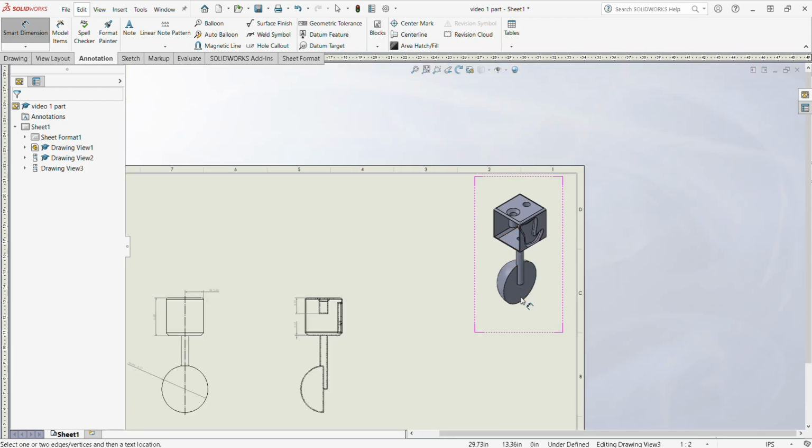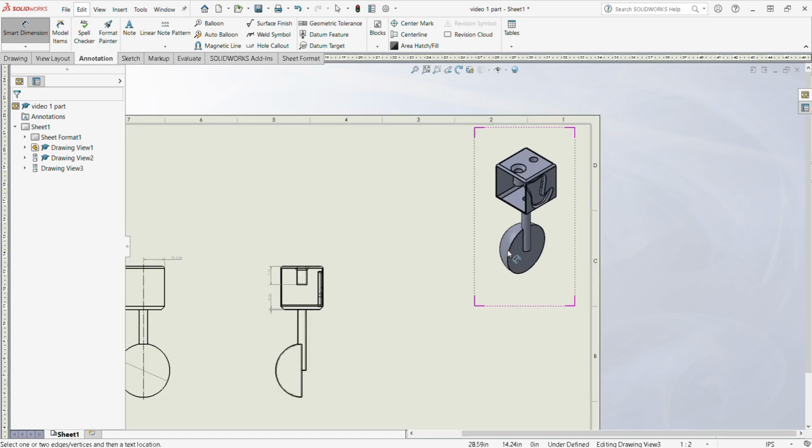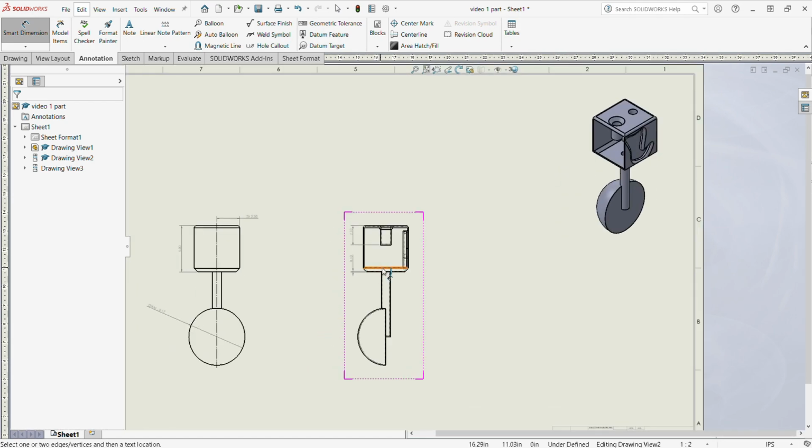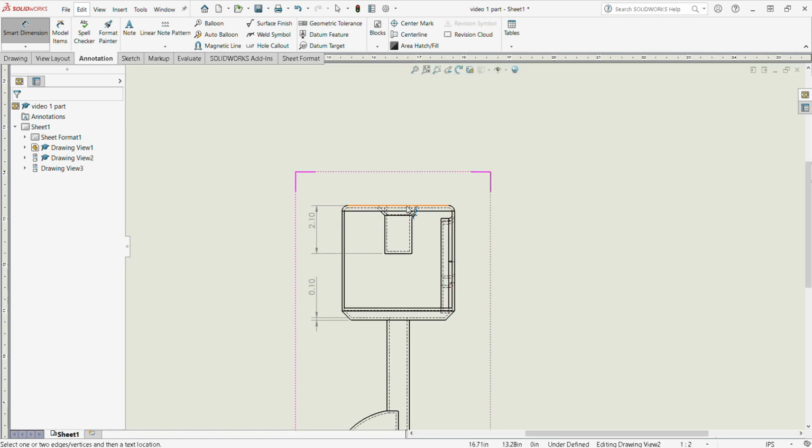This would be an absolute nightmare of a part to machine, or even to print. So keep that in mind. If you wanted to quality control your part, you would take your calipers, drop them down into here, minus the thickness, and say, hey, from here to here, it needs to be 2 inches. And then you see whether or not you're within standards.